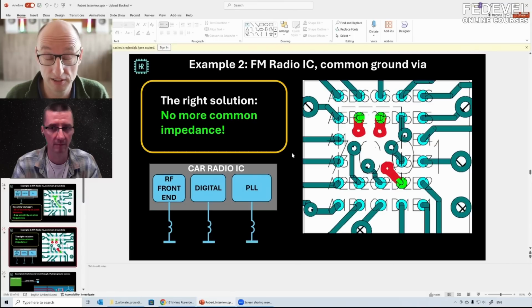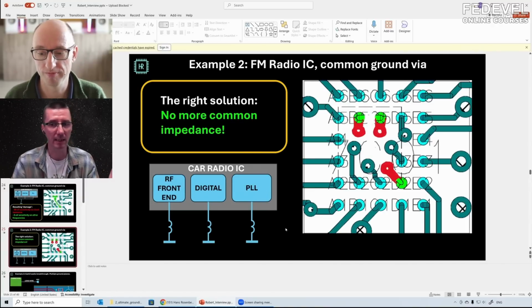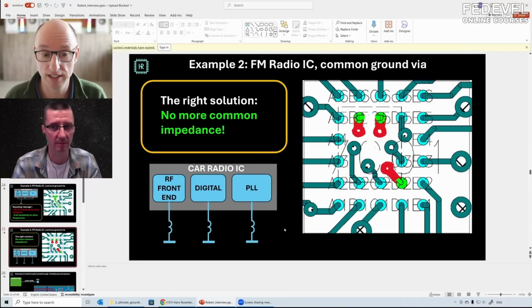If it gets really hard in layout, you can decide what the best trade-off is. Yeah, but in many cases, there is enough space to place a via for every single power pin. I virtually never had that problem, actually. I guess motherboards would be a place where you could...